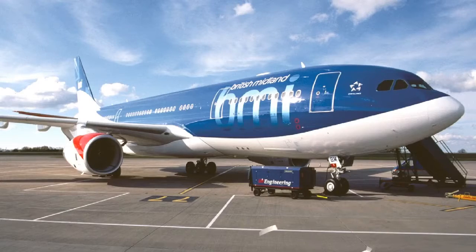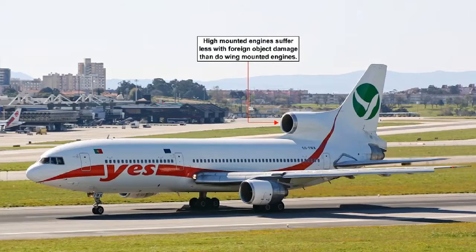This is particularly important in the case of wing-mounted engines, which have their intakes close to the ground. It's no coincidence that aft body-mounted engines, whose intakes are above the level of the bottom of the aircraft fuselage, suffer much less with foreign object damage than do wing-mounted engines.